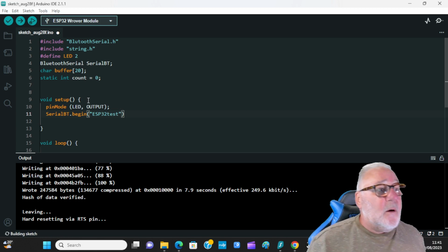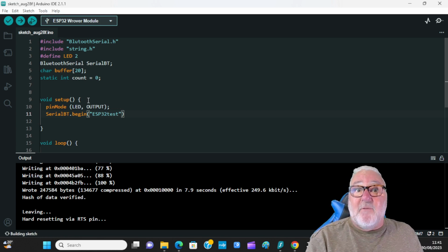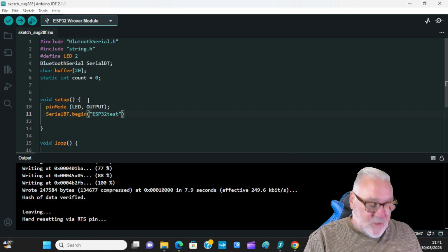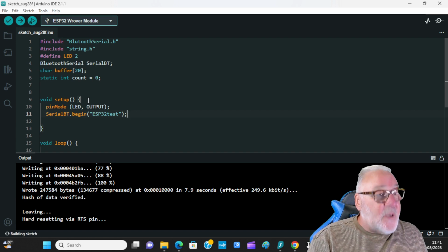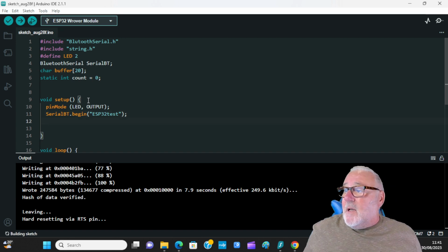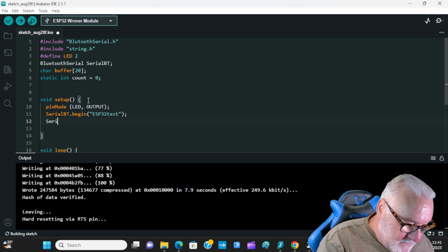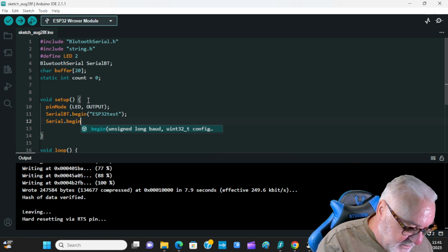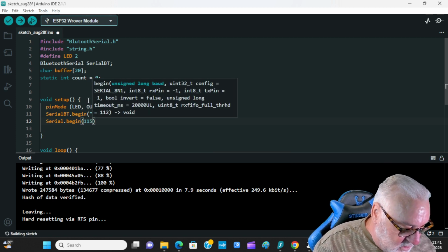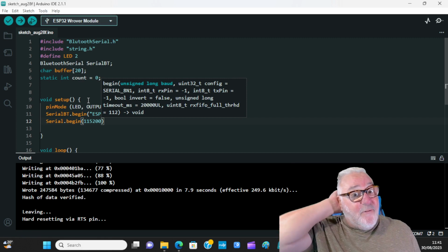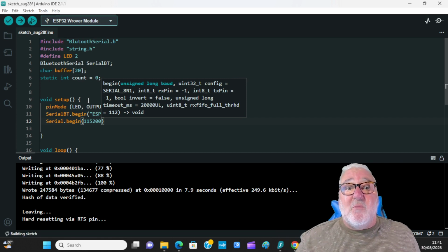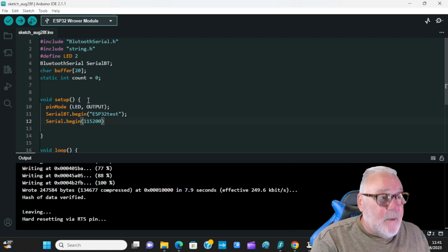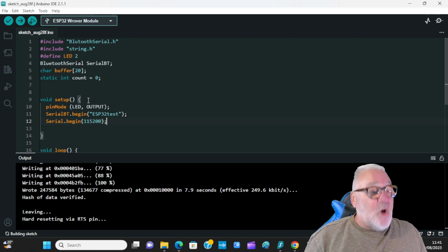Come outside the quotes, come outside the brackets, semicolon, enter. Now we need to do our baud rate, Serial.begin, brackets on, and it's 115200, or whatever you have your baud rate on your serial monitor set to.